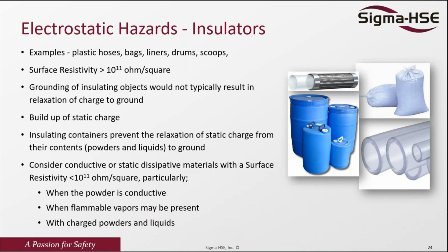Insulative materials are also something that we need to address because they accumulate charges and do not dissipate them. A typical example is what you see here. When you are handling material in any flammable atmosphere, you need to ensure that these materials are not used. You need to have static dissipative or conductive material which you can bond and ground and dissipate the various charging.